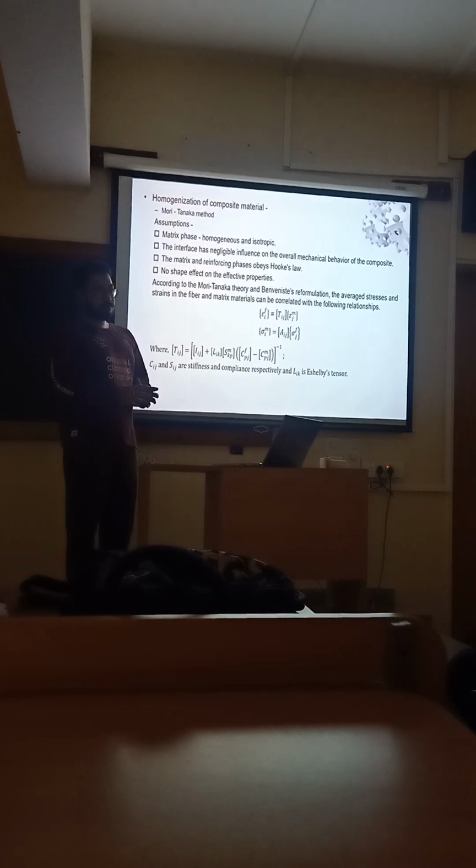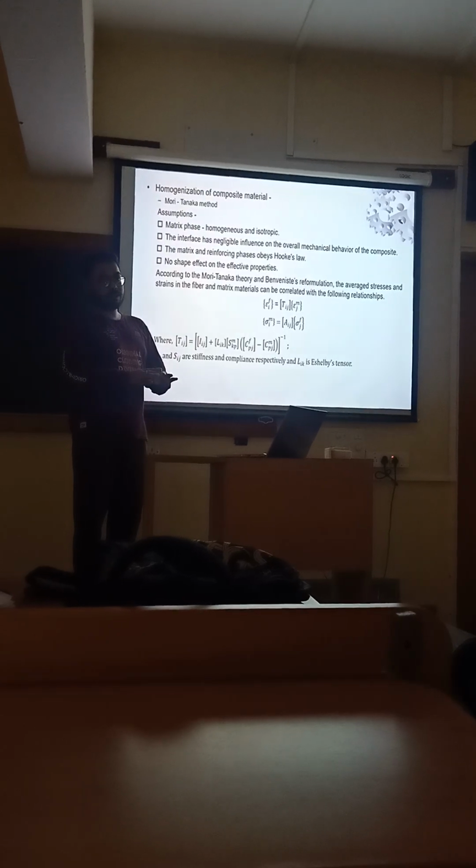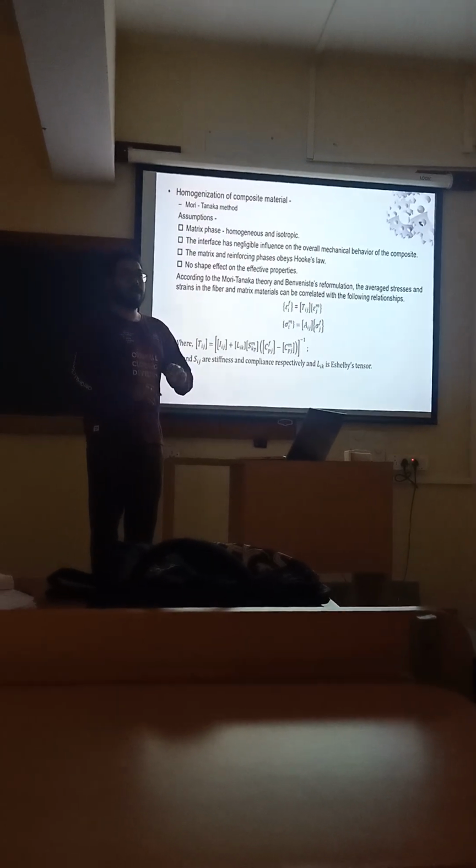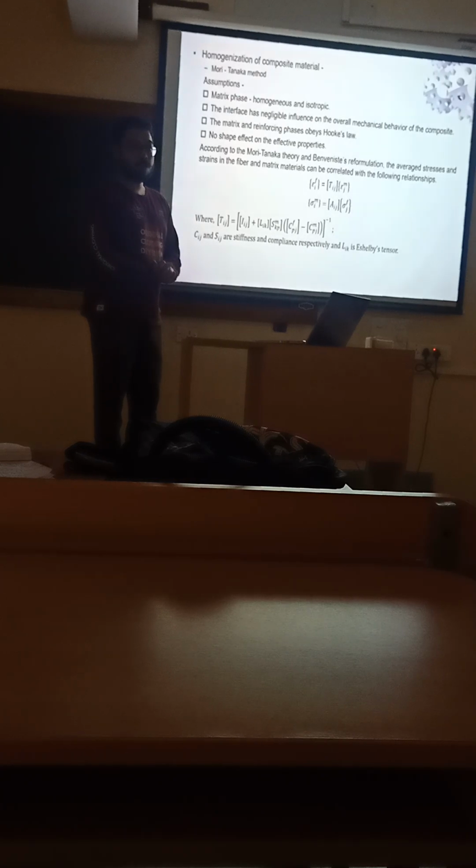See, applying finite element in a beam or in a large structure will give you very accurate results, but simultaneously it involves a very, very costly numerical analysis. So what I have done is, initially what we used to do is homogenize the material. We find the effective properties of the material of this beam, which has 10 layers of laminas that are compressed. So it is basically an orthotropic configuration.